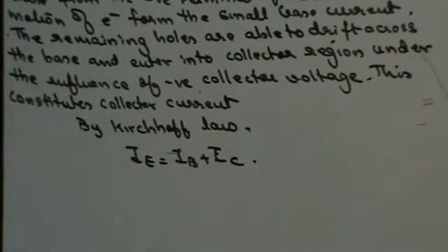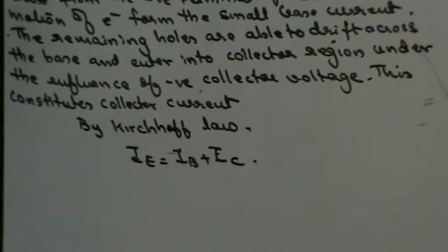Now, do we understand the working of a transistor, how a transistor works? When you have a transistor and put it in a circuit, there are three different ways it can be put. Since it has three terminals, one terminal can be taken as common. So either I can have a common base circuit, common collector circuit, or common emitter circuit. So there are three different types of circuit configurations under which a transistor can be put into the circuit. Fine, we get this clear?